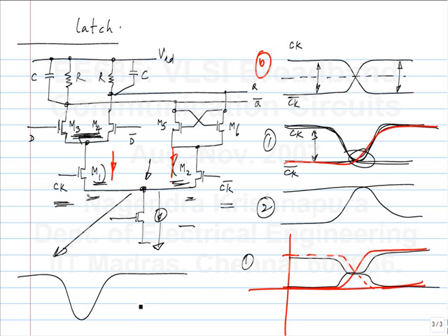In fact, the problem is compounded if you do this. Is this clear? Yeah, that's why this is carrying half the current, this is carrying half the current, both are active. What you want to do for switching is to minimize the period during which both are simultaneously active. And that you can do by a waveform like this. Why? What is this? If differential pair input voltage is 0, both will be off. How come? They will have equal currents, right? So, in fact, this extends the period for which both will be on. So, this can worsen the problem.